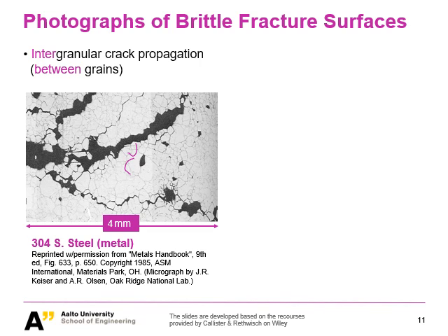You can see they just go like that, especially here. What you probably notice is that the brittle fracture follows exactly our grain boundaries, like this big one here. We call this type the intergranular brittle fracture, indicating the crack propagation is between grains.